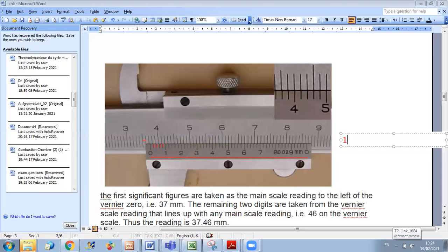So this means that I have 1 millimeter divided into 50 divisions in the Vernier scale. The accuracy of reading will be 1/50, so I can read up to 0.02 millimeter. In this case, the method is the same: I will look at the perfect match.